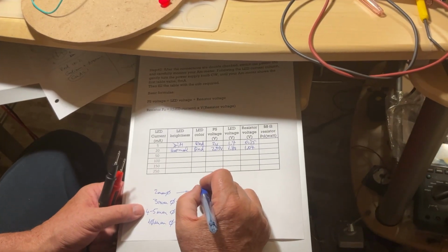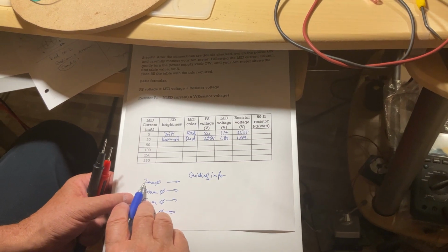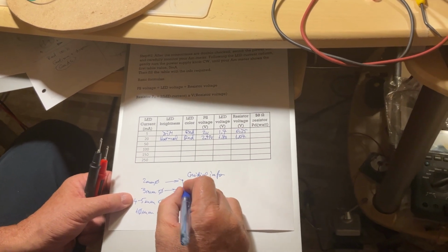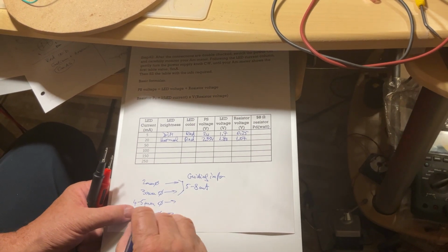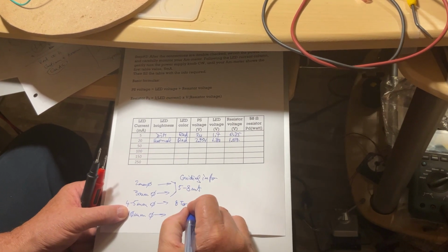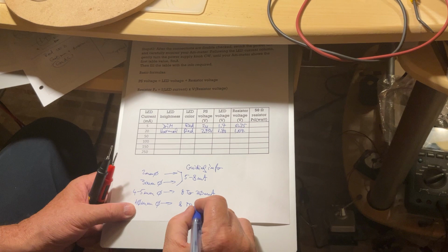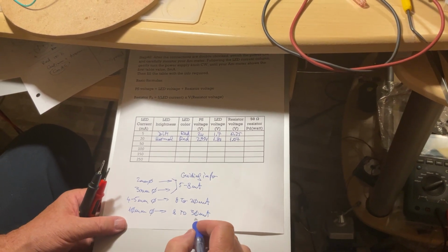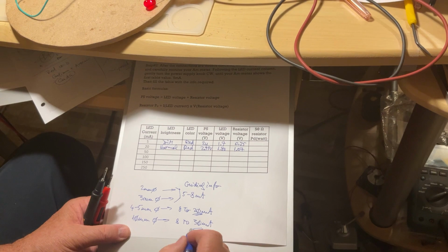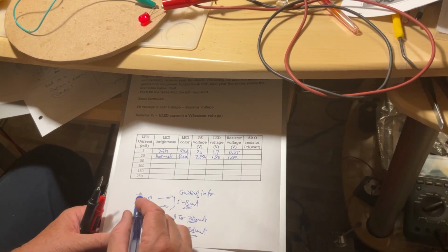Here I'm going to give you an indication, so guiding info. If you want a good light over a 2 millimeter diameter diode, or for both of them actually, it's going to be something between 5 to 8 milliamps. 4 to 5 millimeter diode is going to be anywhere between, let's say, 8 to 20 milliamps. And for the 10 millimeter diodes, anything from 8 to 30 milliamps. So don't overcome 20 milliamps for the 4-5 millimeter diode. Don't overcome 30 milliamps for the 10 millimeter diode. Now we have a 10 millimeter. And don't overcome, let's say maximum 10 milliamps for a 2-3 millimeter diode.